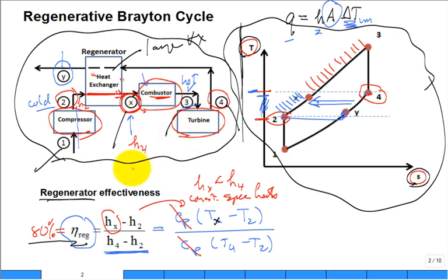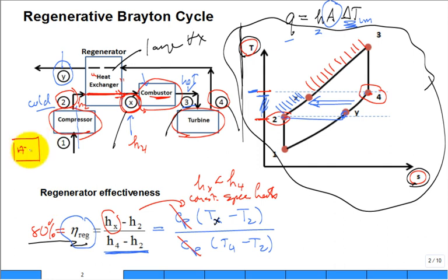And this is where students will be thrown for a loop. Because as shown, is this a cycle where the fluid goes in a loop continuously? Or is something missing that prevents it from being a cycle? Conceptually, you have to add right over here, let me erase, a HX, where you bring this fluid down, so it's coming in at state Y, and then it's going out as state 1. Now I've closed the loop. Because what's really important is there's a heat transfer from this heat exchanger out to the surroundings. You say, well, why didn't they put that in the schematic? I don't know.